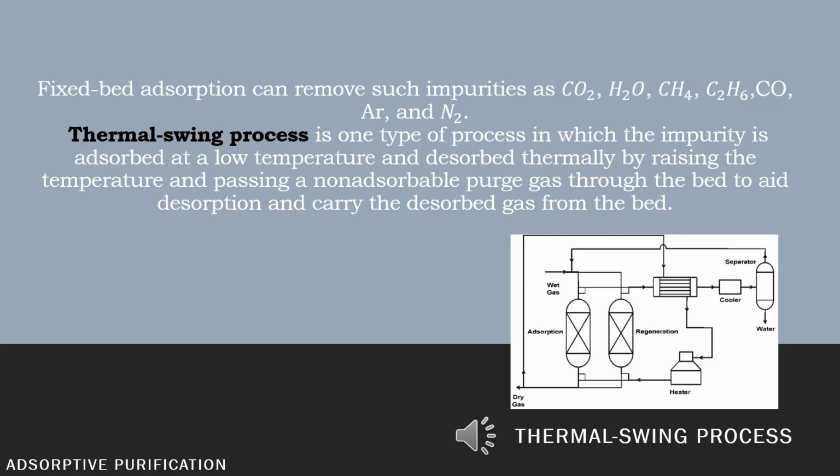So for the adsorptive purification, fixed bed adsorption can remove such impurities as CO2, H2O, CH4, C2H6, CO, Ar, and N2, among others.